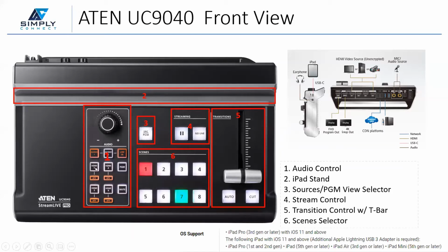So you can see if you press the HDMI in one, the source will change to HDMI in one. And then if you want to have the audio follow the video, you press the audio follow video button. So the audio from the HDMI will follow. But let's say you are mixing the audio with a line in audio, then you need to disable the audio follow video. So you mute the audio from HDMI, and then you enable the line in. You can have the audio from audio one, which is audio one here, or audio 2. So audio 2 is the other audio.